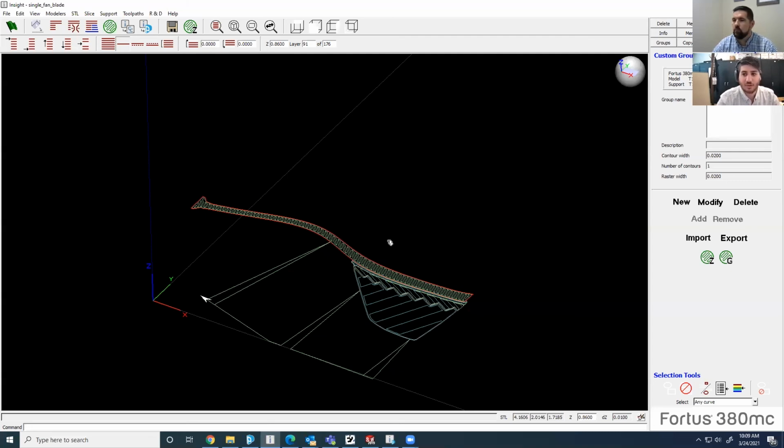Eye protection works well. As you're picking parts, the support material is very brittle. It breaks away and it shatters, and little bits fly everywhere. I recommend picking these parts when they're warm. If you take it out of the oven and you're picking it and it's a rather big part or an intricate part and you need to pick it for a while, as it starts to cool down, the material starts to get a little less easy to work with. So we just put it back in the oven, let it heat back up, and then we're able to work with the support material again.